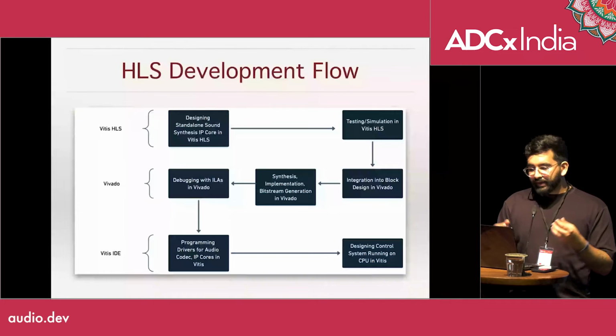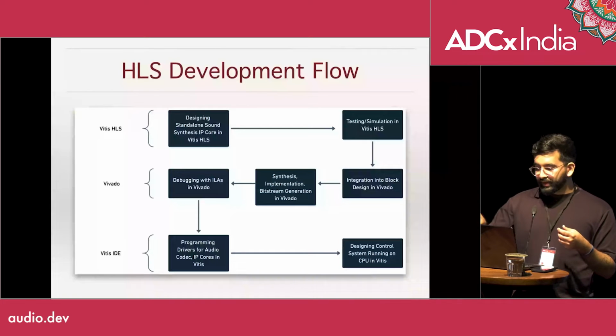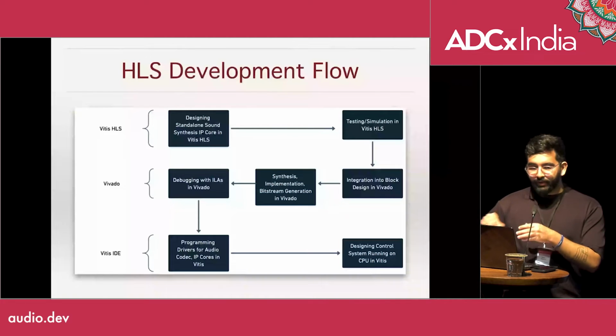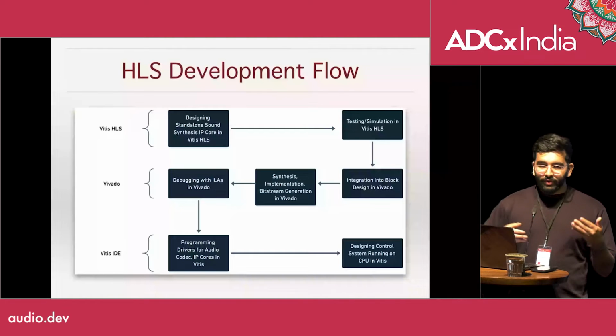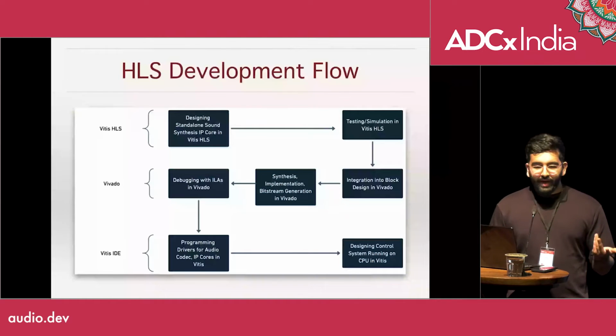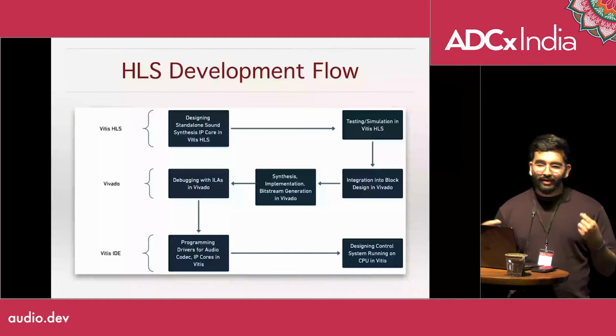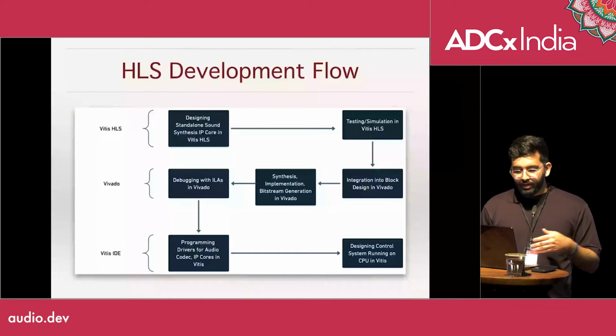So we can think of it like in HLS, we create different parts of a modular system, like oscillators, filters, etc. Then we integrate all of those things in Vivado in a block diagram. And over there, it gets converted into a bit stream, which is flashed onto the FPGA eventually. In Vivado, we can also do debugging with things called integrated logic analyzers, where you can digitally probe your generated electronic circuit on the hardware.